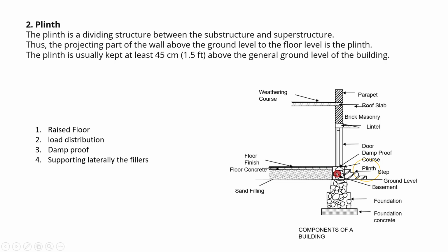And also it provides some safety because, suppose by any chance, due to the bad quality of the soil or ground, the building is settling, if you're not providing this much depth, then this entire building will go below the ground level. So this is meant for accommodating the settlements that may happen, as well as to prevent the entry of water into the building.